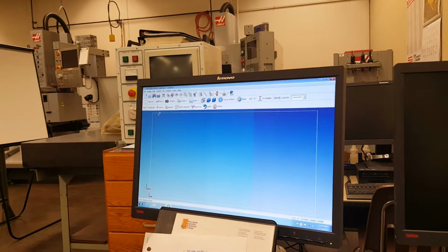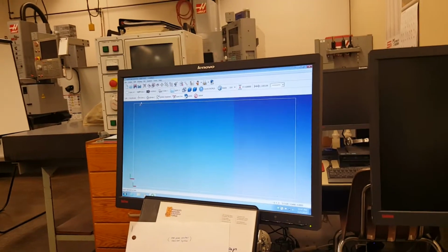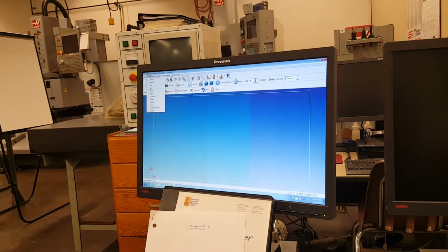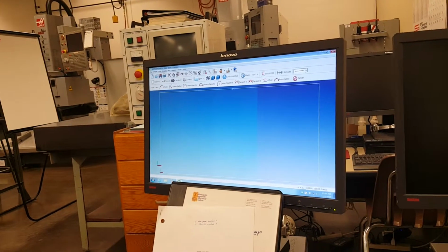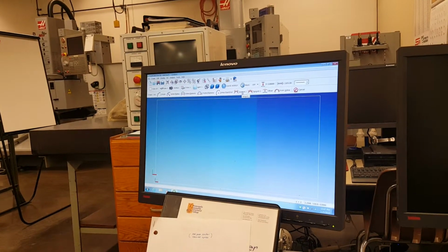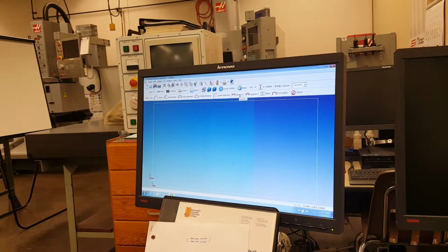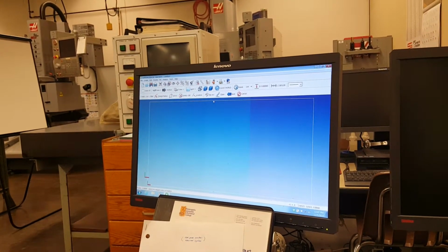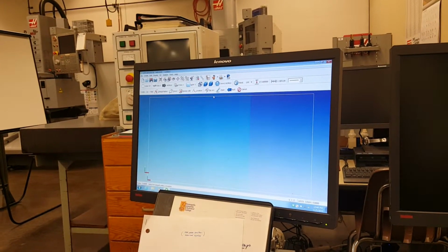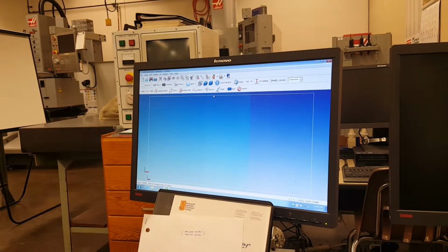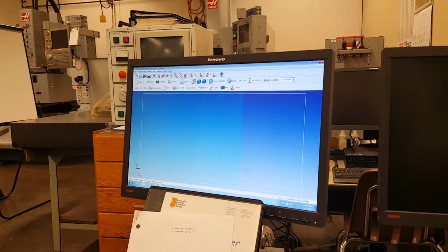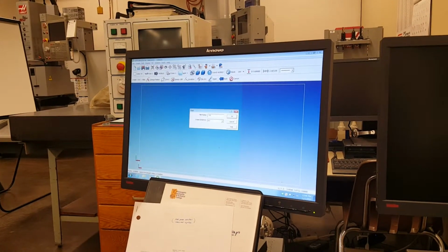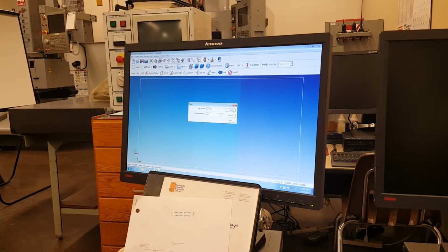Okay, there's a couple of things I see on here. I've got a couple of radiuses. So I'm going to say create an arc tangent to, which means tangent to 2 elements. Okay. And it says that the radius is 1/2 inch on the screen. It defaults to that. But this radius is .375, so I'm going to change my radius to 0.375 and hit OK.